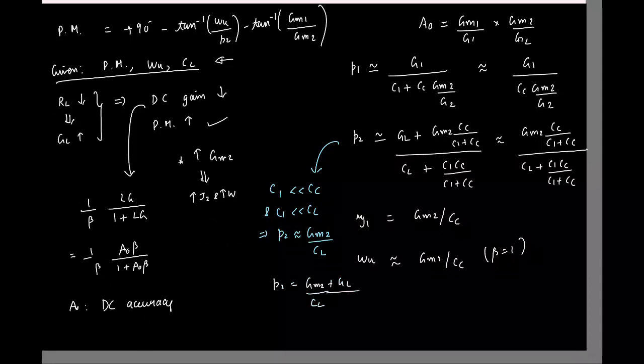Okay. And this should make sense because even when we came up with the two-stage structure, we told that the first stage will provide the gain, and the reason for adding the second stage was what? Why did we add the second stage first of all? So that like buffer will understand. To drive a load, okay, we couldn't drive a resistive load, and that is why we went ahead and put a second stage, right? So this basically is for driving the load. Okay, so whenever the load becomes heavier to drive, it makes sense you go and increase that particular stage.